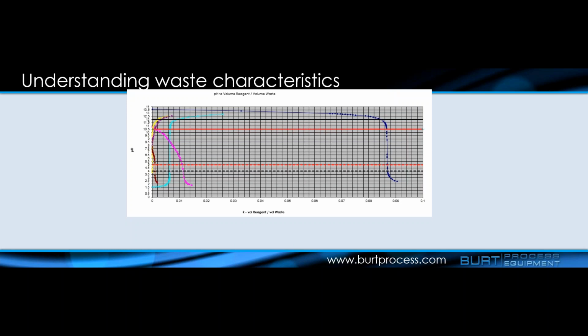You might also want to go to a stronger reagent for those systems, whereby you could then, for example, in this case, we know it's pH 13.5. We might want to use a 98% sulfuric for higher molarity as opposed to the 50% in those cases. But no, the alkalinity treatment will not help a strong waste stream like the dark purple line.